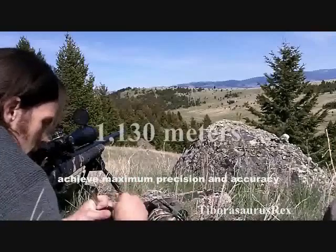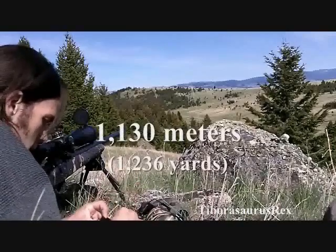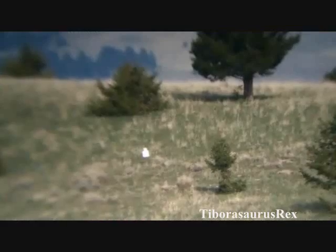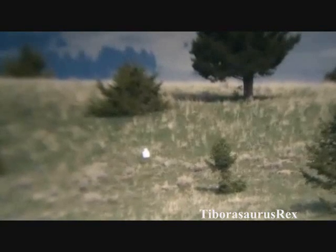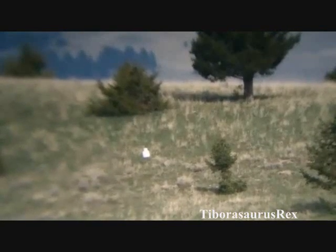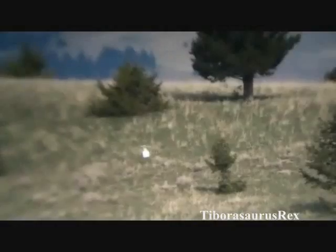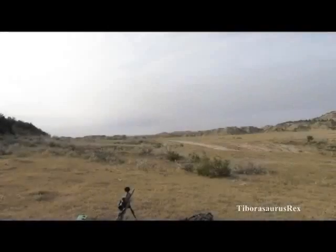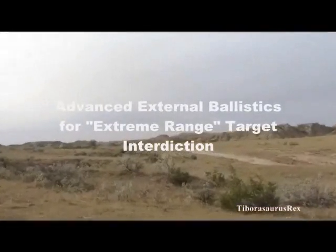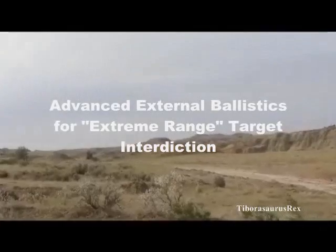So if you have a two-piece rifle stock, you definitely want to make sure everything's real nice and snug at all times. And on certain crucial parts like that, you probably want to use a small amount of Loctite to make sure that stuff doesn't wiggle loose as easily. You don't want to just drench it in there. But making sure that all your screws are tight is absolutely crucial to producing good accuracy, because you want to make sure those harmonic vibrations are as consistent as possible.